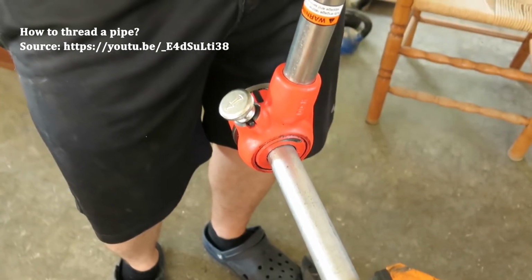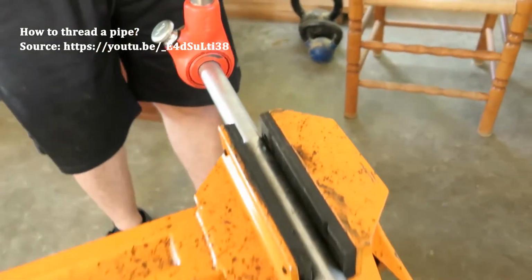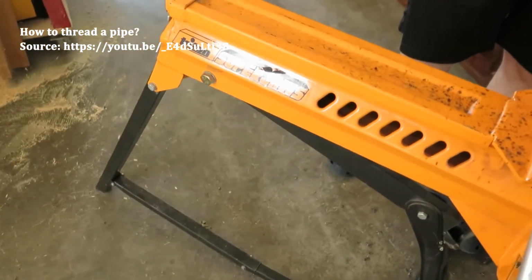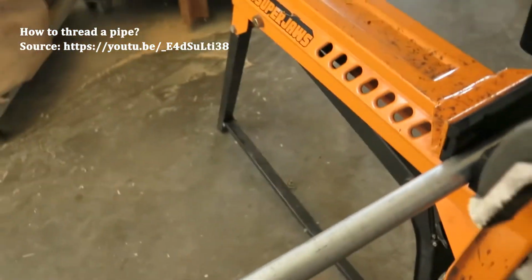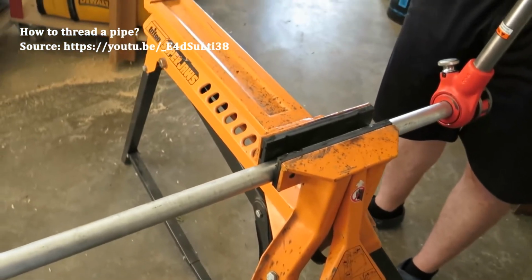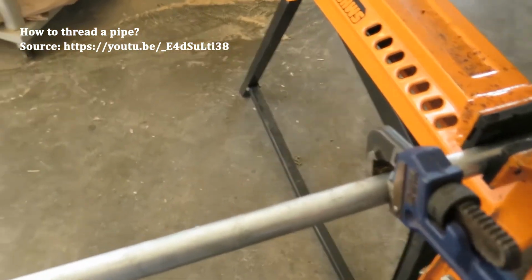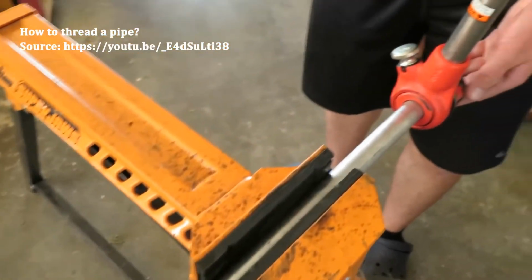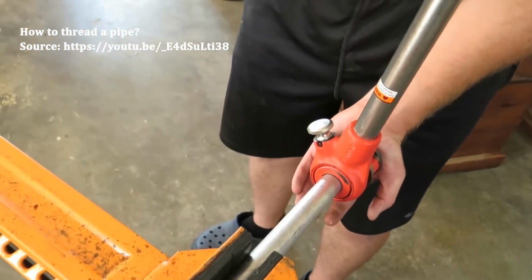So I guess that means it's time for the pipe wrench. So what we have to do, because we don't have an official pipe threading machine or a pipe vise, we just put it in this regular Super Jaws type thing, and then we put a pipe wrench on it, and I'm going to be holding onto this pipe wrench, resisting the turning force that Robert's putting on.